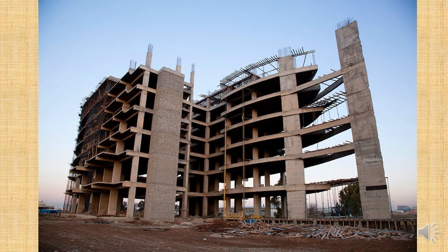Now look at this high rise. You can see here that we've got the superstructure of the high rise already, don't we? So with this high rise, all of the strength is being provided by the reinforced concrete columns. So we now need to fill in walls where you've got all of those gaps with masonry blocks, but they do not need to actually support the load of the building.